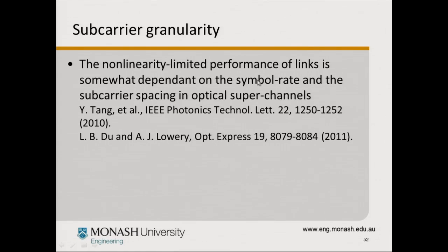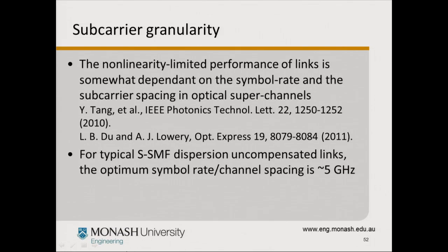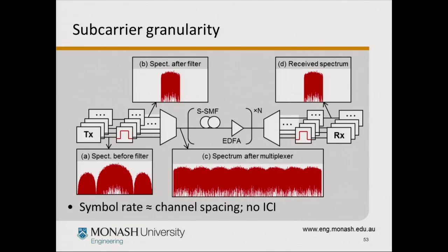Okay, so these papers here have shown that the nonlinear limited performance is somewhat dependent on the symbol rate of the subcarrier. So in this particular case, there's a summary of the results there. Let's assume that we want to fully load up the optical band with the maximum amount of signal, let's say for a terabit per second a channel or beyond. We'll have to use multiple optical carriers.